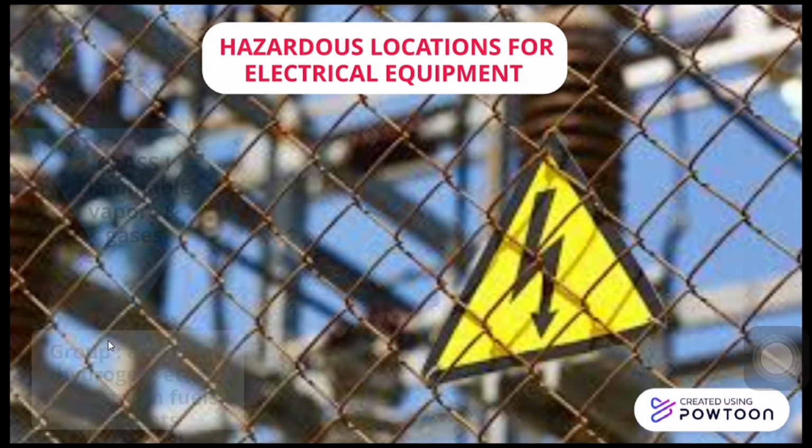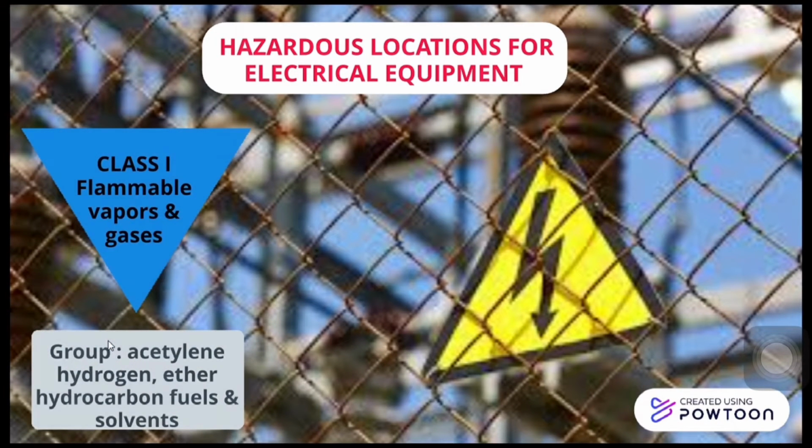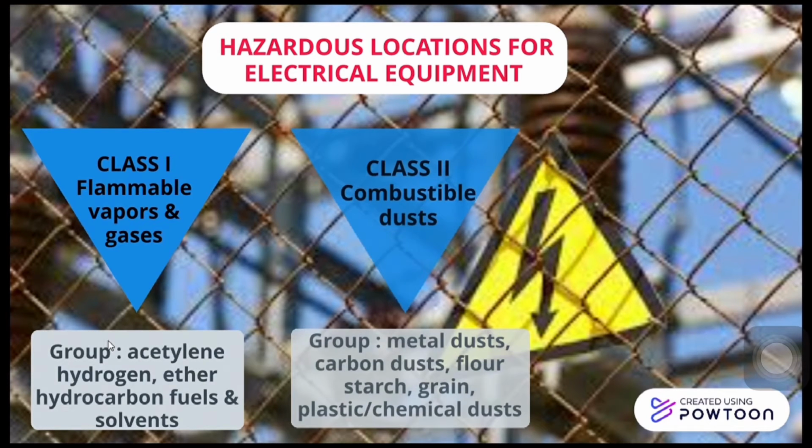Moreover, the NEC classifies hazardous locations for electrical equipment. There are three basic classes: Class 1 for flammable vapors and gases, Class 2 for combustible dust, and Class 3 for ignitable fibers.